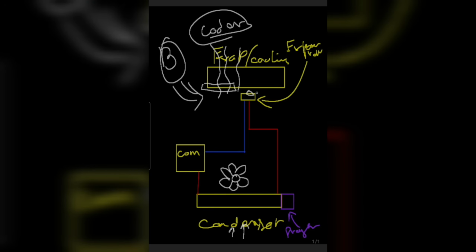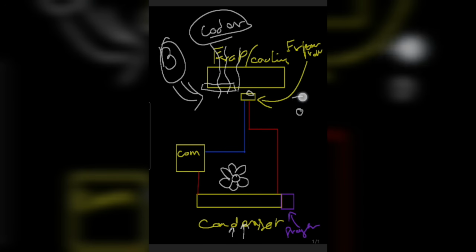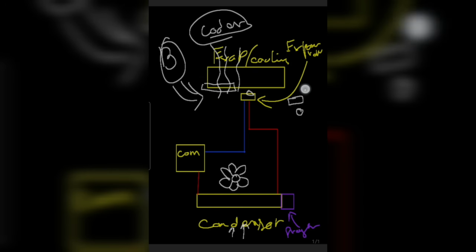action takes place right here. What happens is this thing passes through a very small hole, and all of a sudden it gets a larger area to open up. In this part, this high pressure gas gets converted to low pressure very quickly. That's why this coil cools down to a very cold temperature, and then, as I explained to you, the